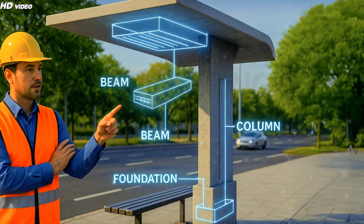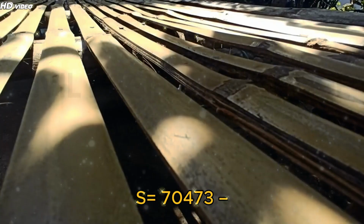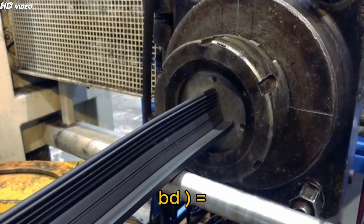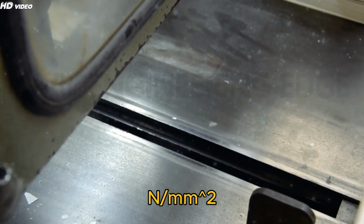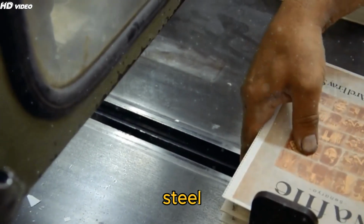Maximum shear force SF equals 62,710 Newton. Nominal shear stress equals SF / bd equals 62,710 / (300 x 560) equals 0.37 MPa.